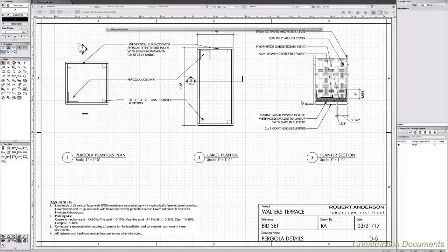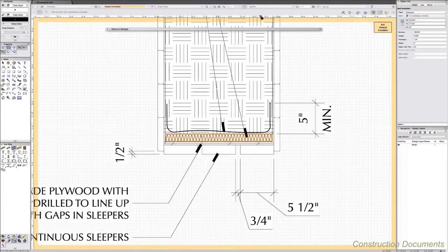And there are times where you're working on the section, you realize, I forgot to incorporate how the corner posts and this planter are going to be fastened. So I had to make some modifications to the BIM model, but then I showed this material here for the drainage board. That's literally just a 2D thing drawn in the viewport of the annotation space. So it's not going into a whole lot of, I've got to model that thing exactly too. You use the general concept and then you embellish it with line work. Exactly.